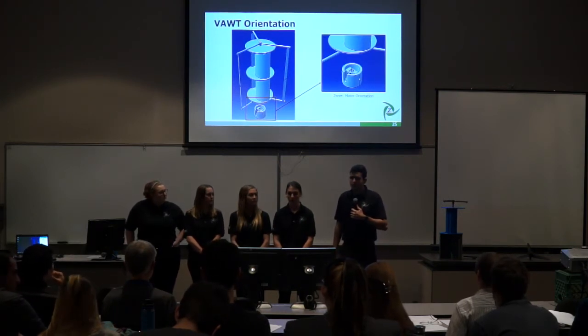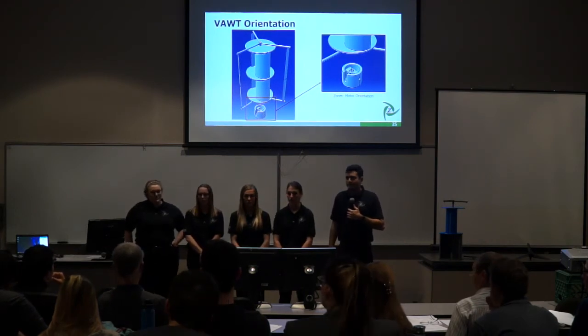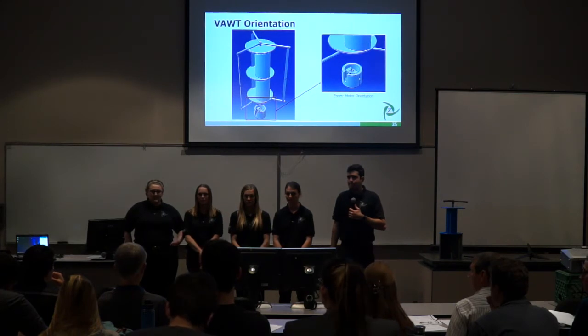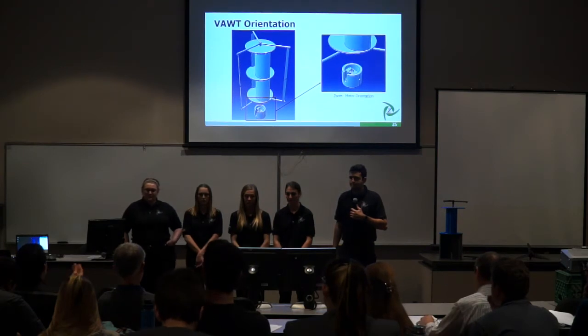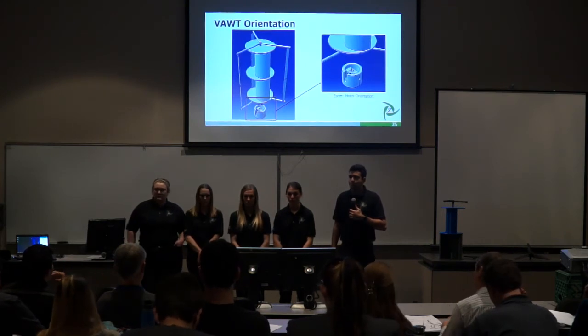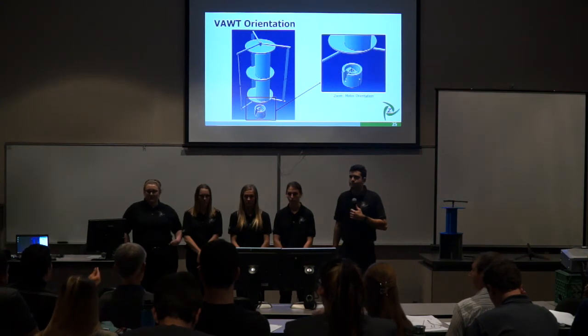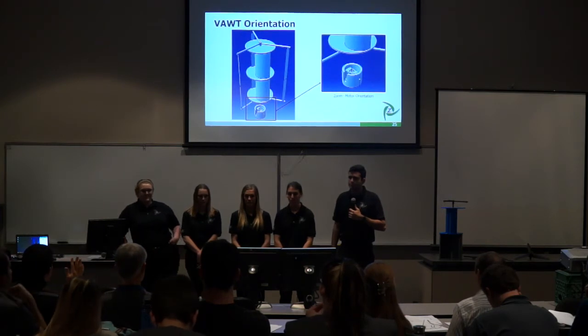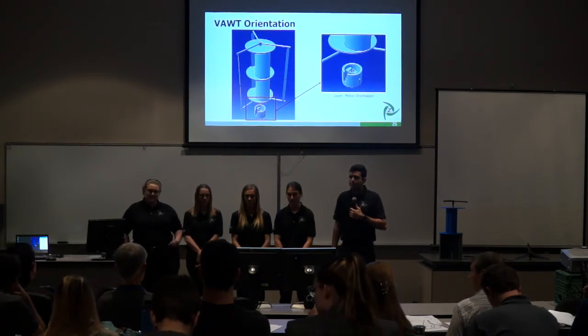We were going to do a vibration analysis on the blades to ensure that they don't break themselves. Yeah, you might want to look at that. You're limited in the types of modal analysis you can do. You're not going to do a ground vibration test on it, probably. But you could do that in ANSYS at least. Find the natural frequencies to make sure you're not stepping into any of those in your range of operating conditions, maybe figure out how fast this thing should actually spin and make a recommendation. You're definitely going to want to look at that.